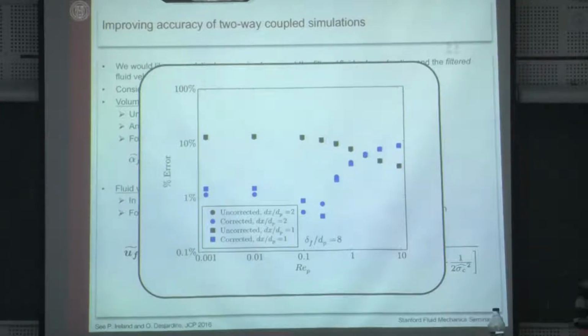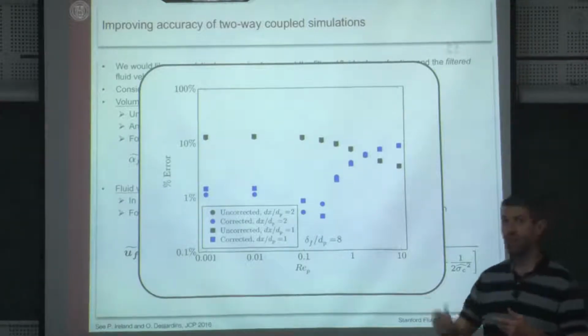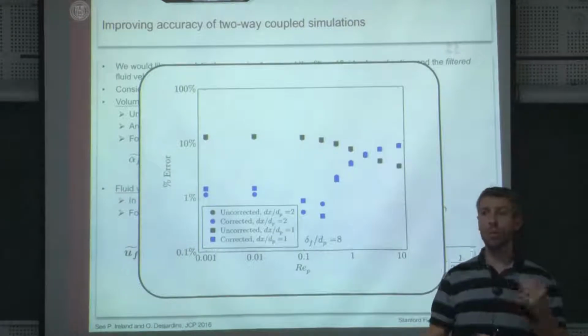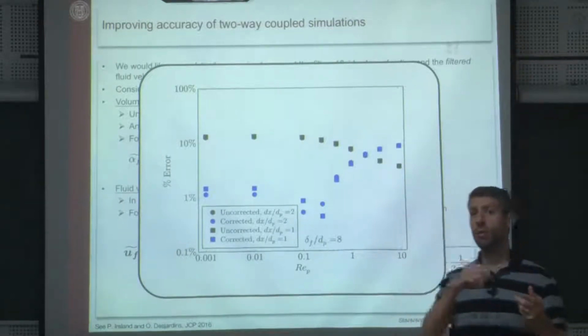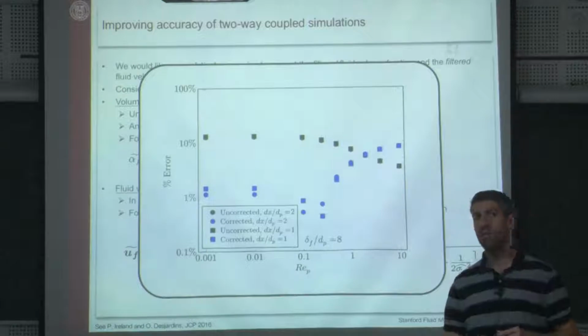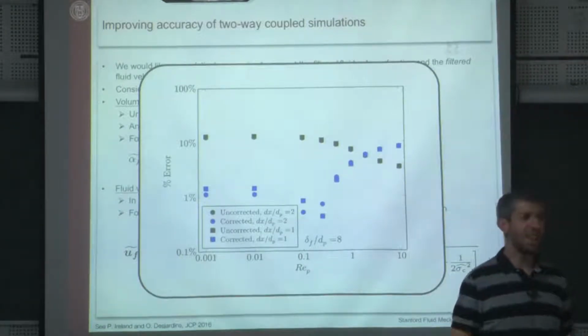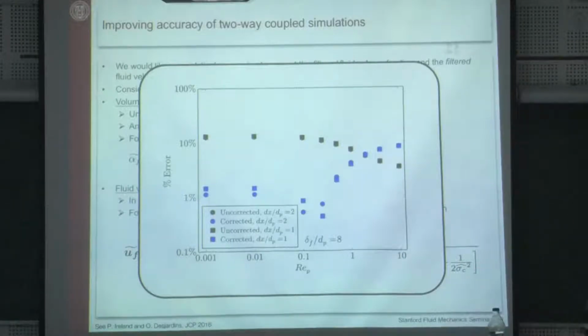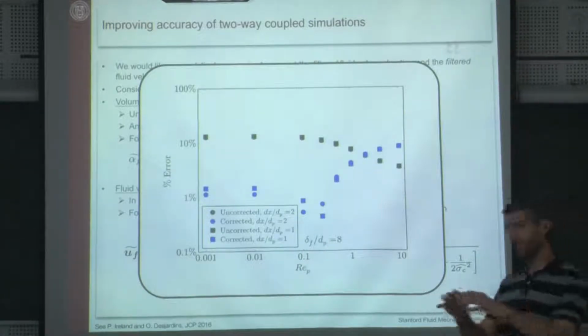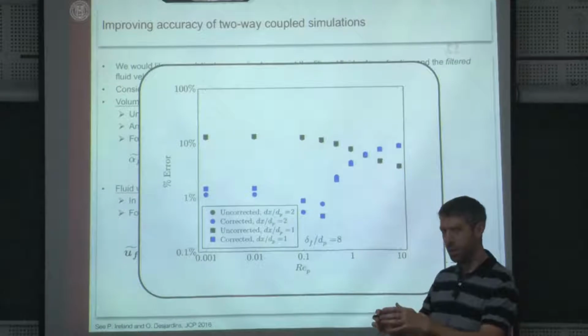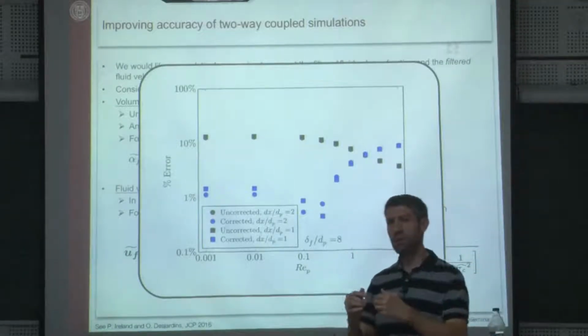Instead of trying to account for the existence of curvature and the way it modifies drag, we're going to say that any type of local curvature in the flow field probably comes from the fact that the particle has modified the flow field itself. The issue with this is that it's very tunable, and they didn't really show better performance for high Reynolds numbers, but I think this is also a very interesting idea. It is more pragmatic. Instead of saying I have something analytical about my flow field, they say, I don't know what to say, but if my flow field is very locally curved on the scale of the particle, most likely that's my fault, so let me remove that.